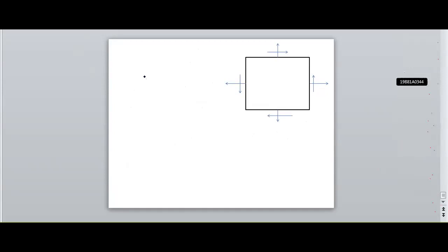We have learned it in engineering mechanics. Now this is the force, the resultant, at 60 degrees. I need to resolve it into the perpendicular and the tangential components. So the angle here will be 30 degrees.